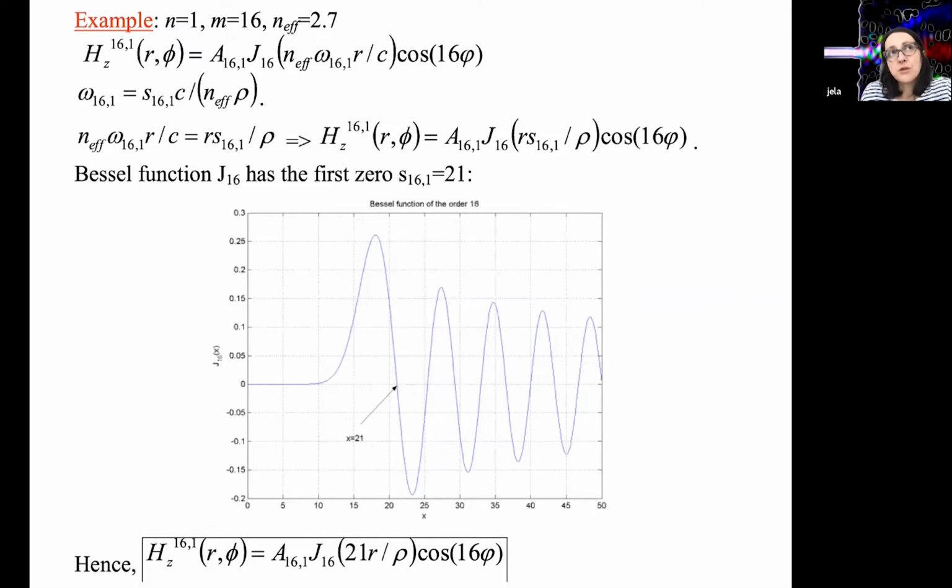But you know that you want to build a system that specifically operates at 1550 nanometers. Maybe you're building a laser for some fiber optic communication system, so you want 1550 nanometer operation. That's where your quantum wells are. Thickness is 220 nanometers. Operating wavelength is 1550. You know the refractive index of indium gallium arsenide phosphide at that wavelength is around 3.4. So you find the effective index of 2.7. Okay, so we already found that.